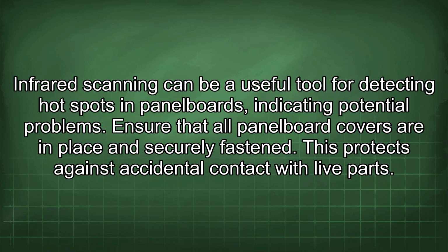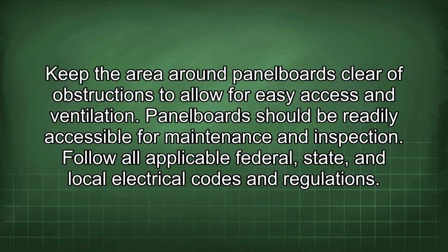Infrared scanning can be a useful tool for detecting hot spots in panel boards, indicating potential problems. Ensure that all panel board covers are in place and securely fastened. This protects against accidental contact with live parts. Keep the area around panel boards clear of obstructions to allow for easy access and ventilation. Panel boards should be readily accessible for maintenance and inspection.